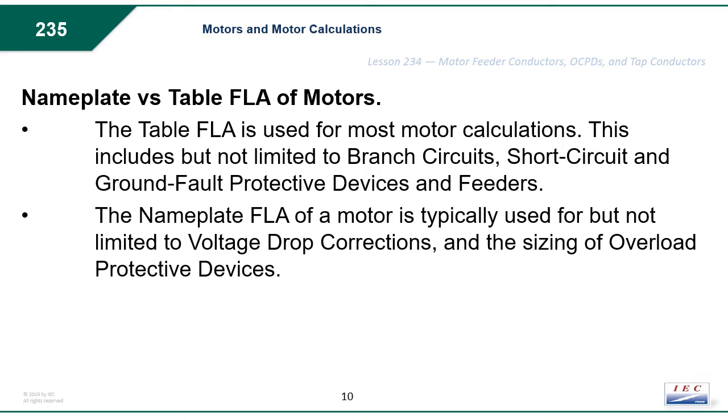The nameplate FLA is typically used, but not limited to, voltage drop calculations and the sizing of overload protective devices or heaters. That's typically the only areas you're going to use nameplate FLA for. Voltage drop corrections and the sizing of overload protective heaters in these scenarios.